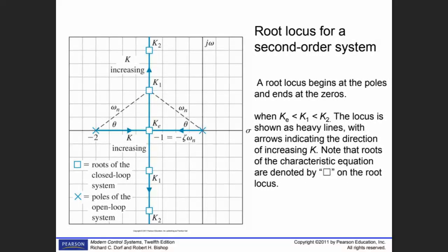However, you obtain those curves. And then while you are moving your cursor on top of it, you can see the value of K, you can even obtain the zeta, and you can easily decide which kind of K value is most appropriate for your application.